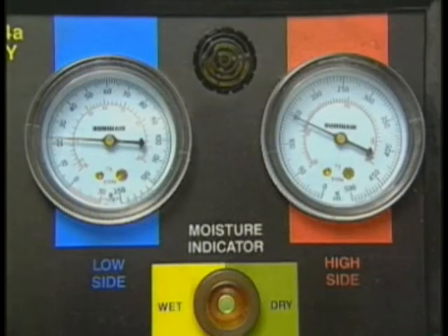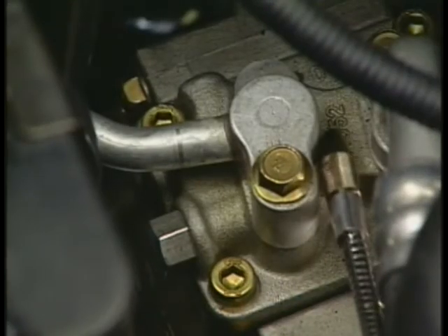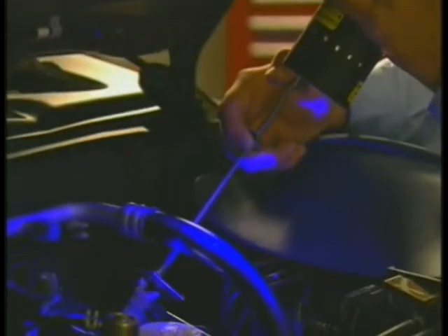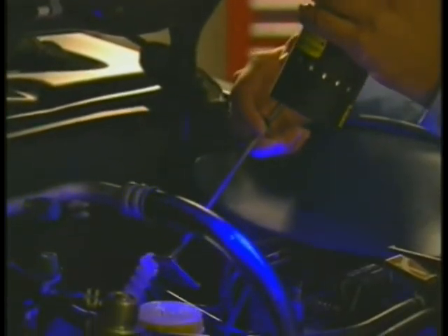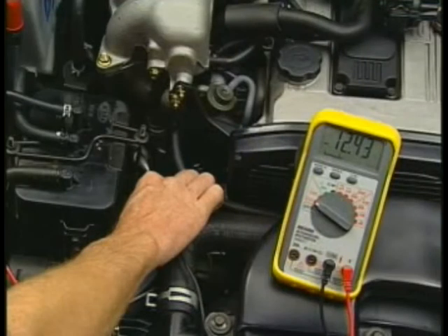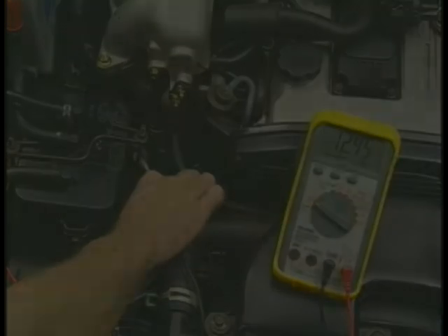Pressure gauges to measure the pressures on the high and low side of the system will give a quick indication of how the refrigerant is flowing through the system and identify possible problems with components. Electronic leak detectors can be used to find the source of refrigerant leaks, as can fluorescent dyes that can be added to the refrigerant charge and show the leaks when exposed to a black light. And lastly, digital multimeters and scan tools are indispensable when troubleshooting the controls and system protection devices that we will look at in the next presentation.